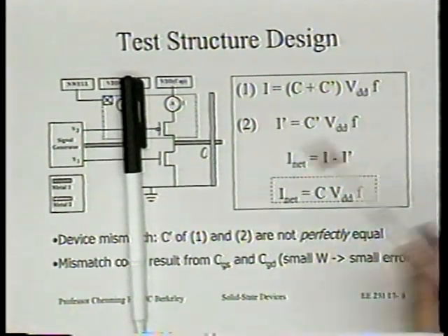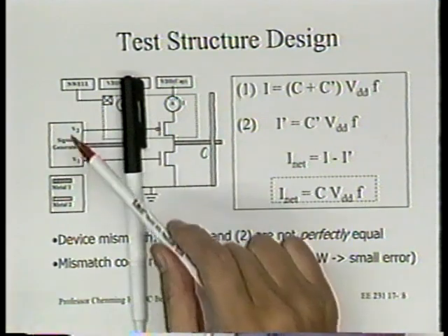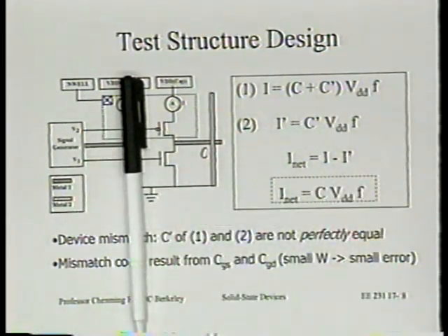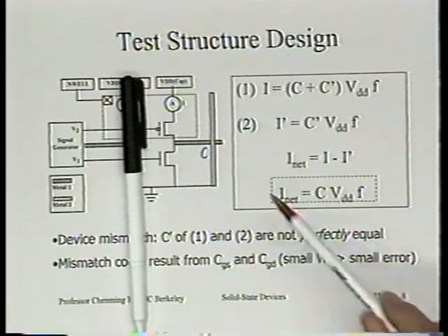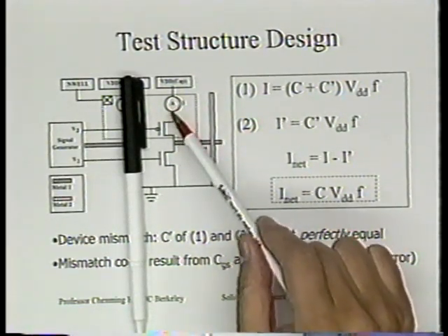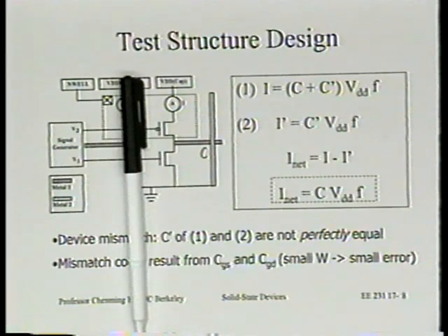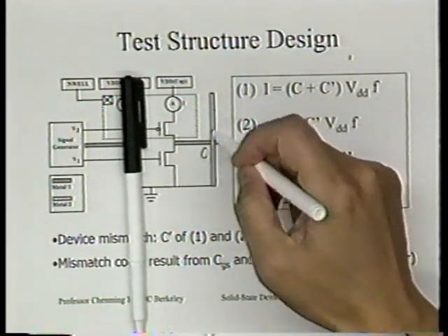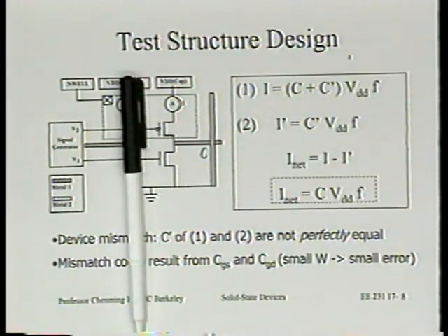It's a clock which is generated on chip, by the way. So the students designed the chip, a simple circuit to generate this clock on chip. And externally, we only put a DC ammeter in there, right? Then we connect to VDD. All right. So the remaining question is how sensitive it is. Now remember, keep in mind, 10 to the minus 14 is actually better than the capacitance we need to measure. Okay. Let's see what we have.